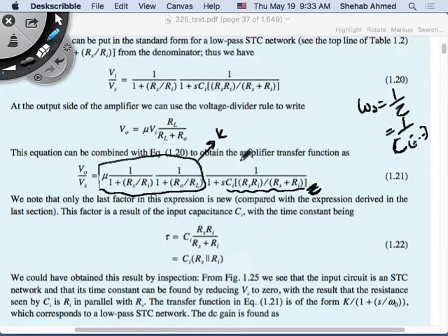So you went that route, right? That's one way to derive this relationship between V output and Vs. There's a smarter, simpler way to do it. So we know that this is a single time constant circuit, right? So there's one approach to quickly come up with what I want. I want to come up with my gain, and I want to know if this gain is frequency dependent.